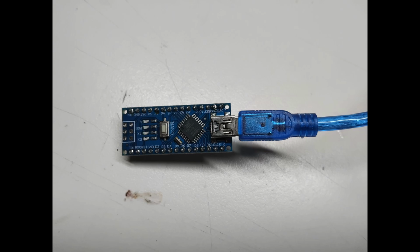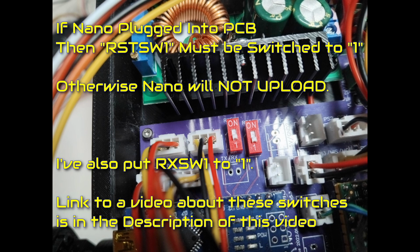But if we have the Nano fitted into the PCB board, there's a couple of switches. This RSTSW1 switch must be in the 1 position, which is the off position, otherwise the Nano won't upload. I've also put the other switch, the RxS1 switch, to 1.